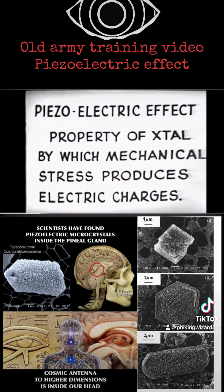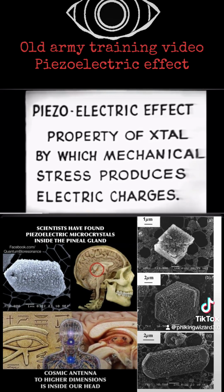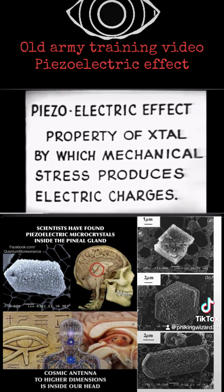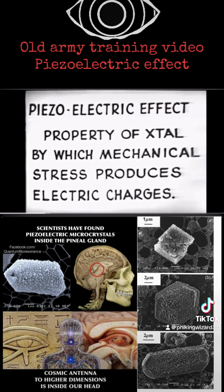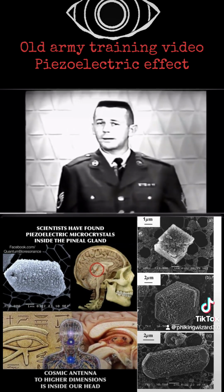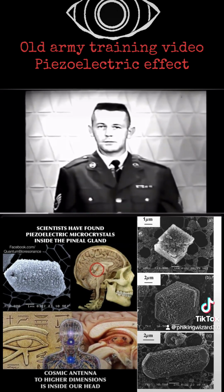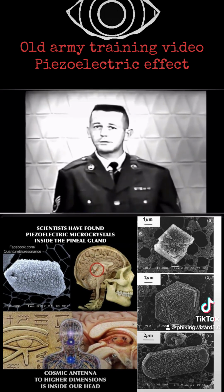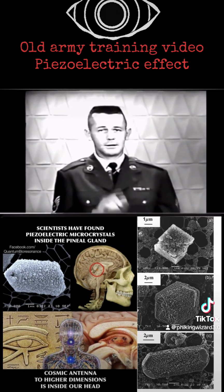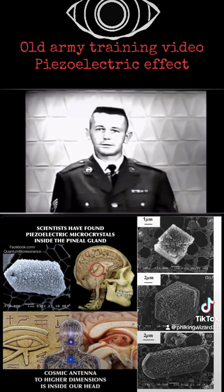Now, the piezoelectric effect is defined as the property of a crystal by which mechanical stress produces electric charges, and conversely, electric charges produce mechanical stresses. Now, this is saying nothing more than if a voltage is applied to the crystal, it will vibrate. The amplitude of these vibrations is much greater at one frequency than at any other frequency. Now, this one particular frequency is called the natural resonant frequency of the crystal.